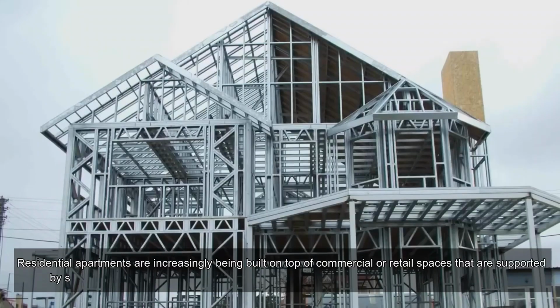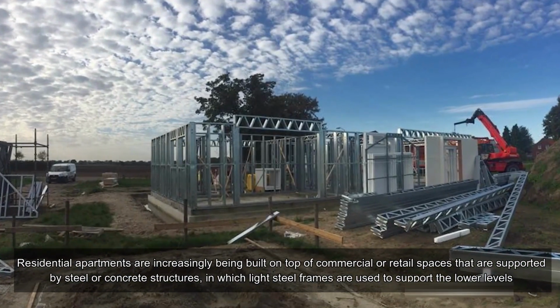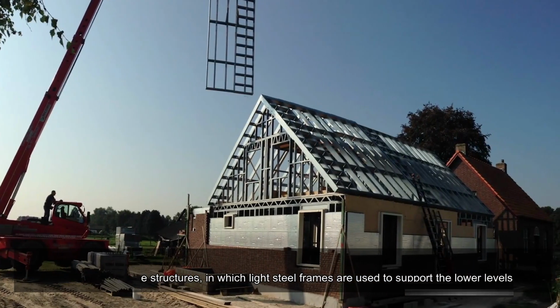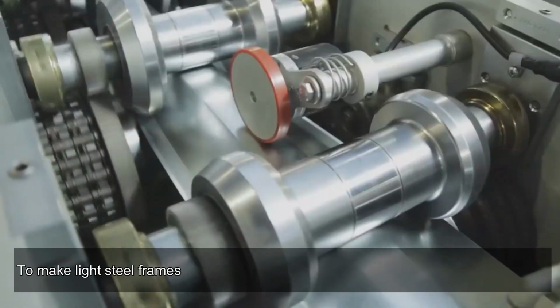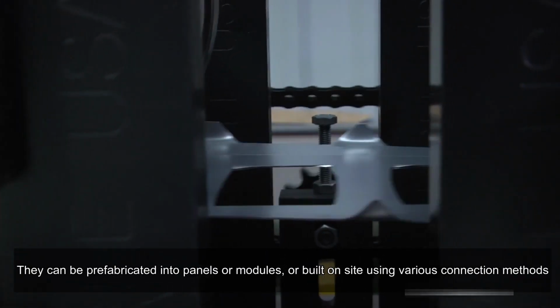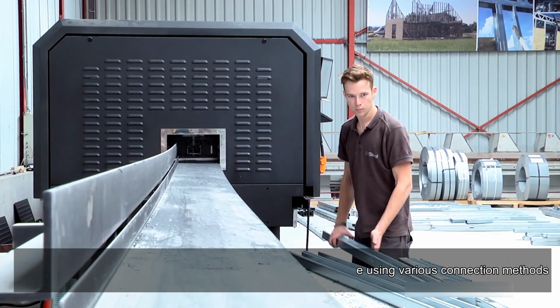Residential apartments are increasingly being built on top of commercial or retail spaces that are supported by steel or concrete structures, in which light steel frames are used to support the lower levels. Methods of steel structure construction. To make light steel frames, cold-formed sections are used as the construction blocks. They can be prefabricated into panels or modules, or built on site using various connection methods.